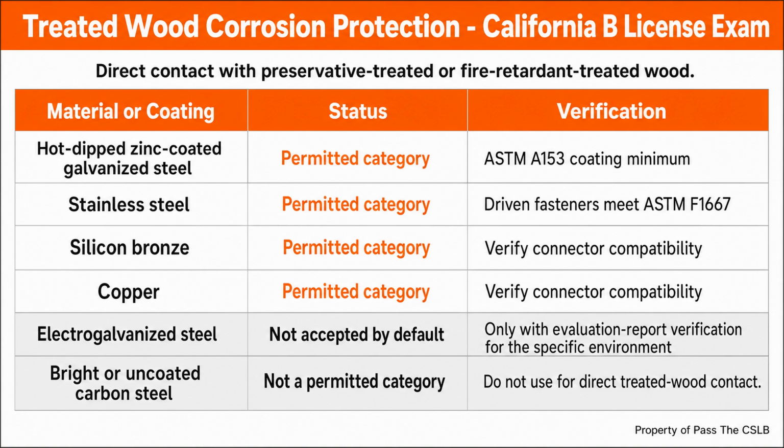Approved alternatives may exist: a different listed connector, an approved structural connector screw, or a revised engineered detail may solve the problem. The general boundary is that the field crew does not create the approval by making the alteration. The supporting documents must authorize the configuration.